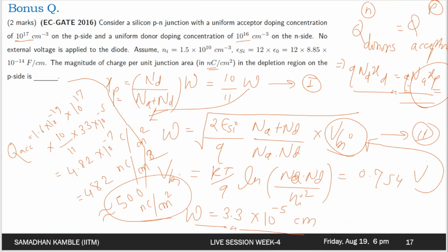Because we are considering a bulk semiconductor here, and in bulk, so three sides you can consider, it is volume. So charge per volume is considered. In your case, you are saying charge per area. So that density is different. Yeah, that is surface charge density. What is expressed in the lectures is the volume charge density.